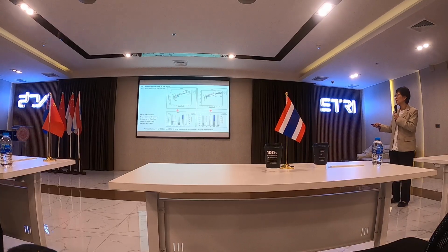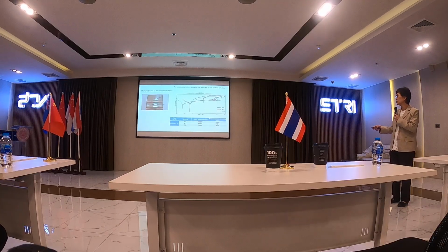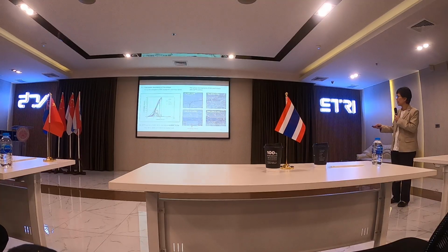And then this one we study the passivation technique, like using nitric acid, a just polished sample without any treatment, and treatment with sulfuric acid with hydrogen peroxide, and then we test for pitting corrosion. This one is again with the welding. With the welding at this point, the welded area cannot be passive at all.